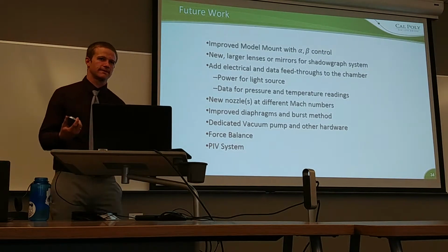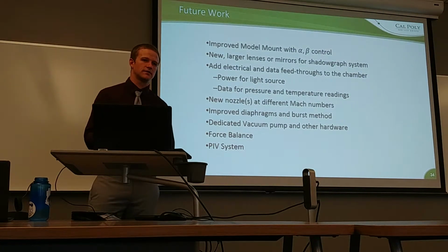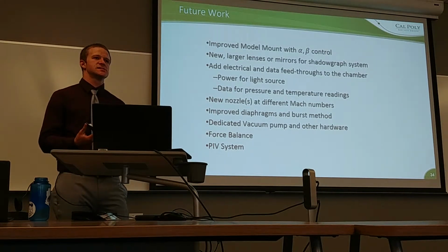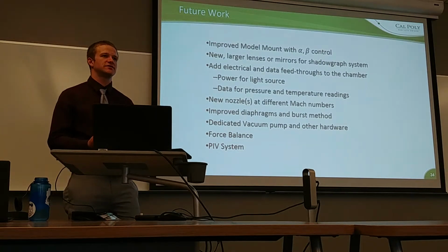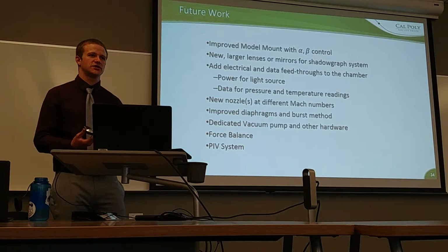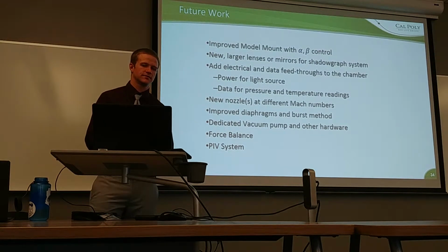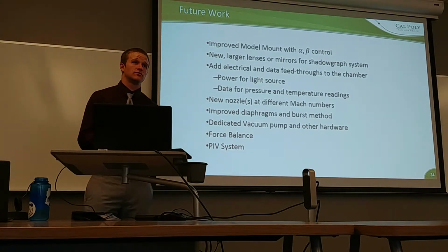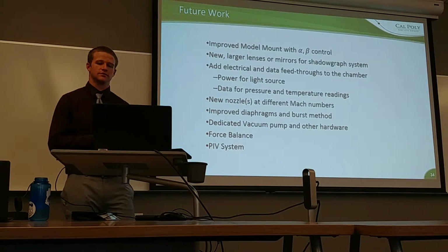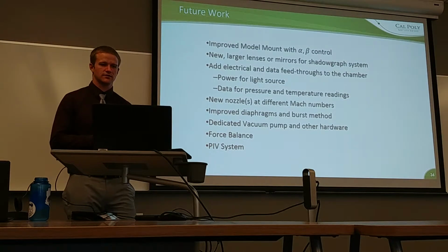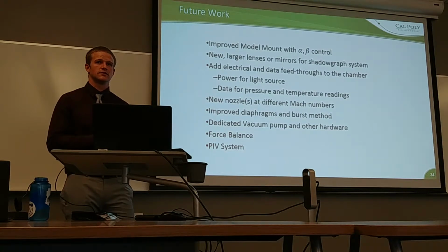Huh. Just out of curiosity, did you look at the Mach number at which the shock would have detached from something of this angle? You mean the angle at which the flow would have detached at this Mach number? As Mach number goes down, there's some Mach number where you no longer have an attached wave shock. You have a detached shock, which is what a bow shock is. Right. I'm wondering if an alternate explanation could be that for some reason your Mach number was lower, and that's why you got bow shock. But anyway.